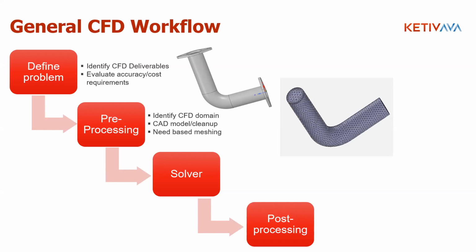The other thing is meshing. When you're doing pre-processing, meshing the domain so that it gets divided into those individual control volumes that I talked about in the previous slide, that part is important, right? Now, depending on whether or not your flow is internal, external, which areas need more refinement, which areas have more flow gradients, you might want to spend some time on understanding, how do I mesh my domain, right? Which areas are important? Which area am I looking at? Does the mesh need to be fine in this region? So all that comes in the pre-processing part.